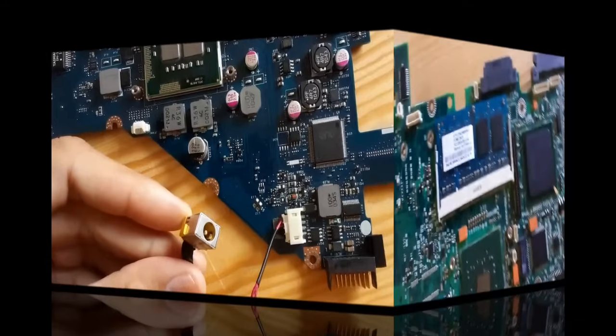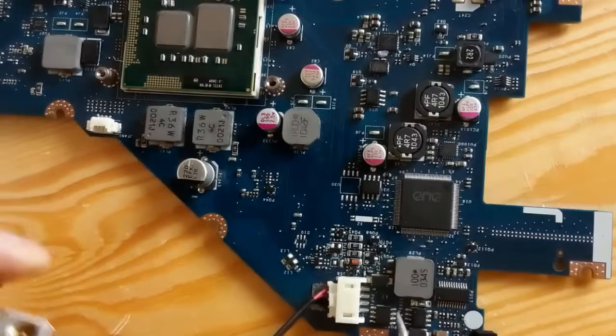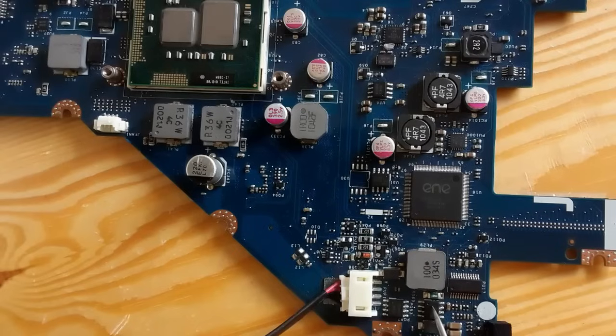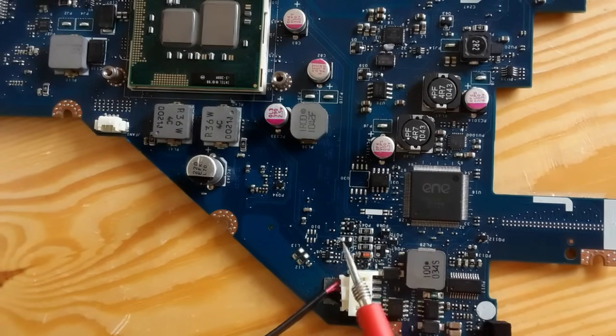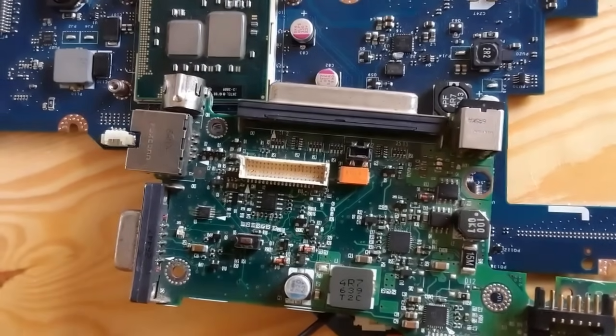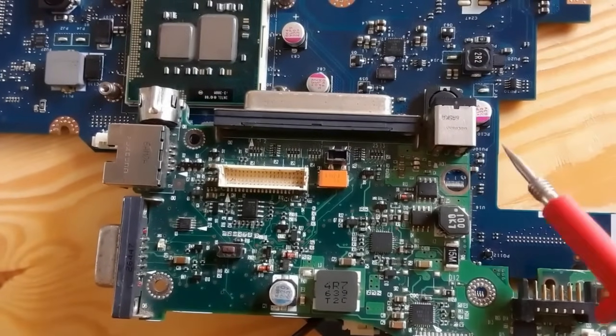As you can see, we're going to see the switches. Okay, so the switches or the MOSFETs, you will always find near the power jack or the power jack connector, two switches or sometimes one switch. These switches are the gate of power in every motherboard. Among the common faults in the laptop motherboard are bad MOSFETs or bad switches.